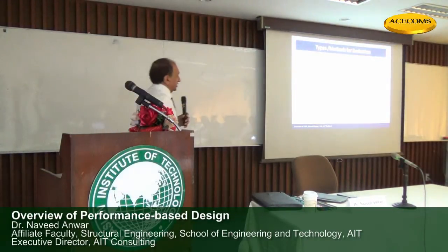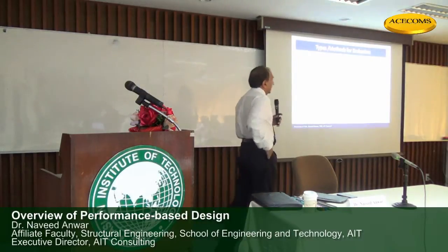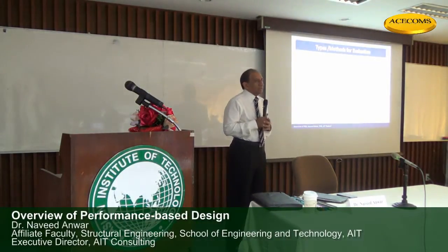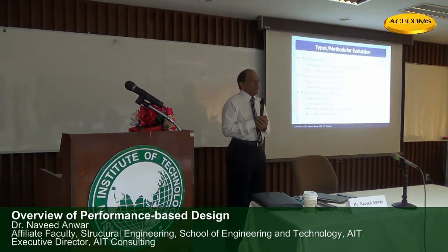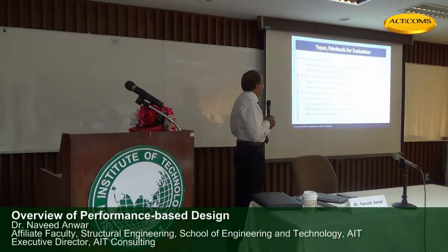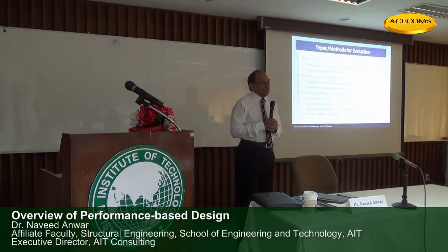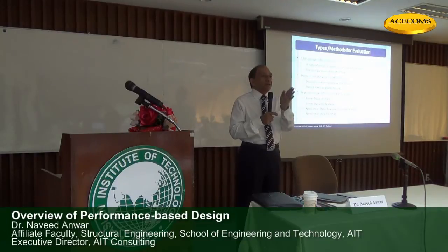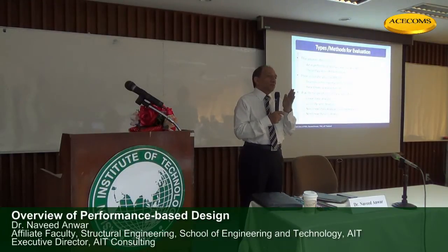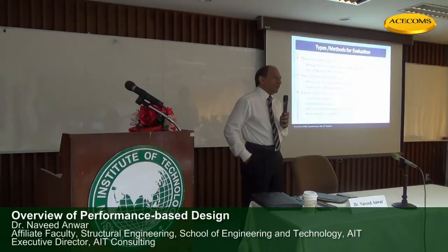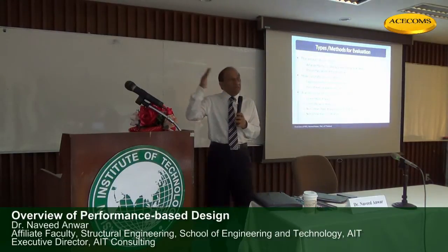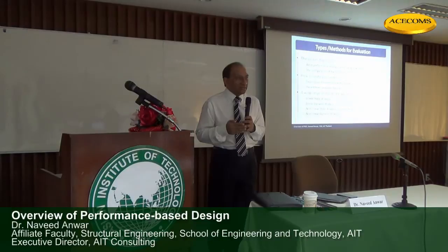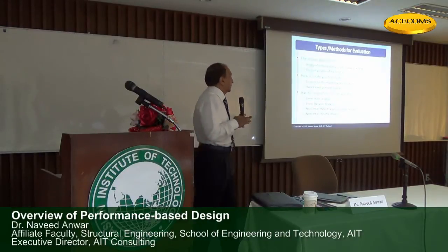How do we do the evaluation? How do we do that? And the answer will depend upon what is the objective. What are we expecting from this performance evaluation? What performance levels are to be achieved? If we are only expecting the elastic or the frequent performance level to be achieved, design is easy because it's elastic. We don't need to do much. But if we are expecting the MCE performance levels to be achieved and checked, it's complex, highly complex.